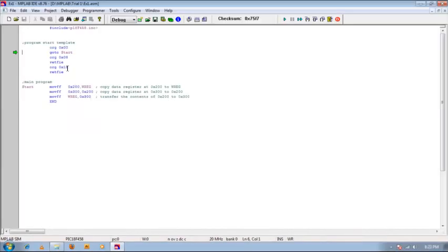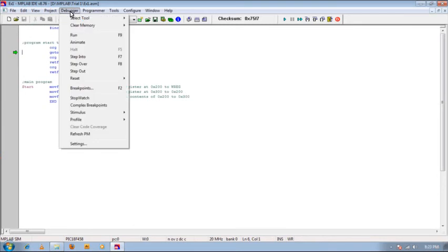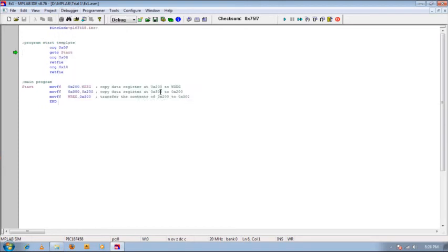So how we are going to start is, again you go to the Debugger tab. You need to reset the microcontroller. So you go under Reset, then Processor Reset. The shortcut is actually F6. It would be good if you can remember this. When you click Processor Reset, you can see the green arrow. This green arrow represents the program counter. So currently the program is pointing at address 0.